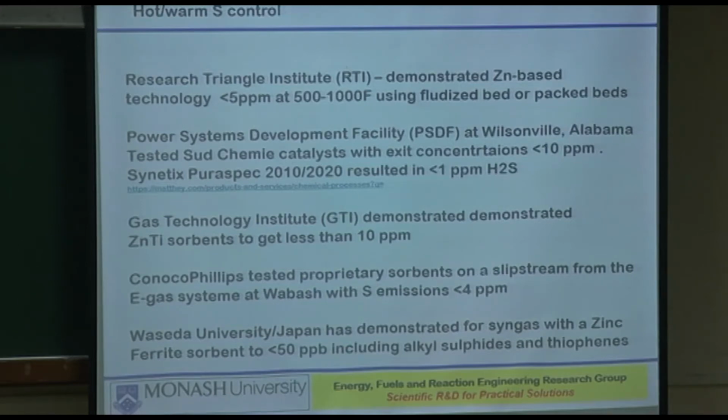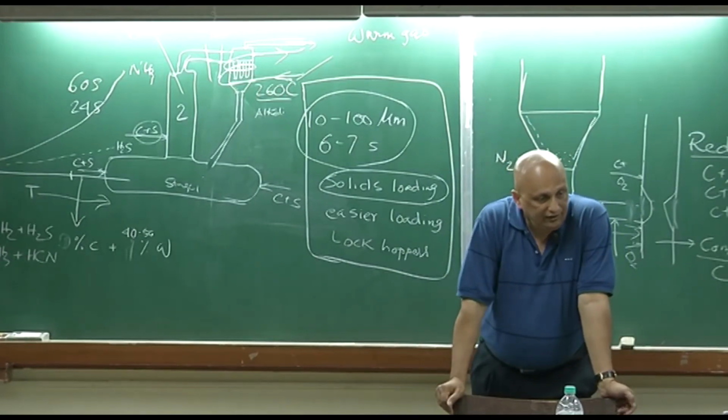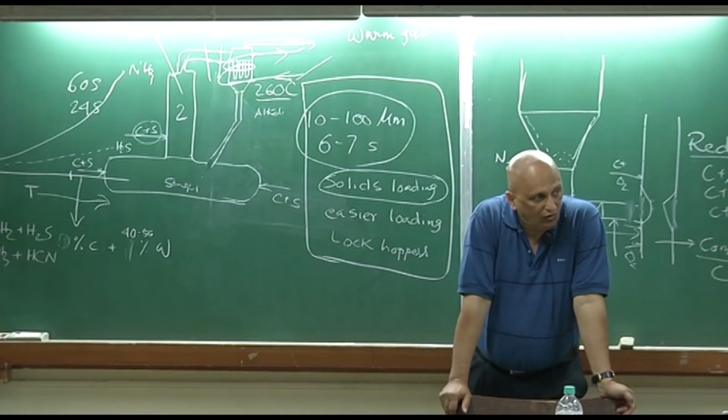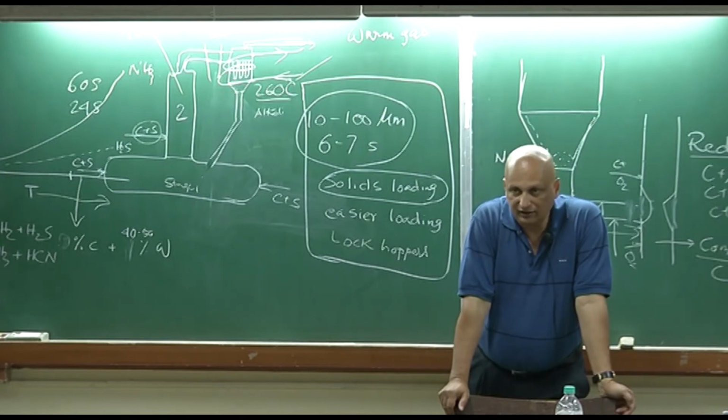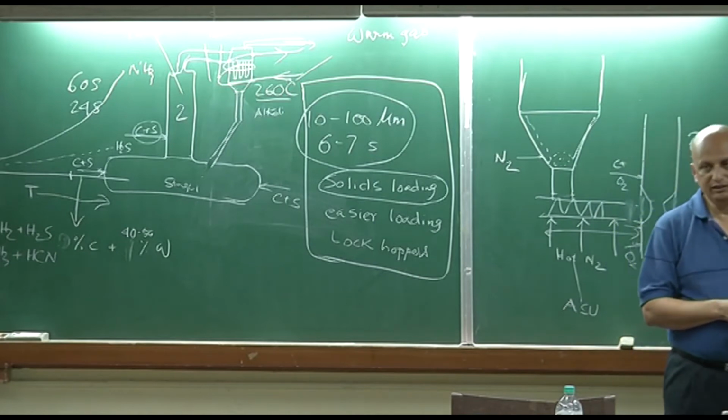But their filtration system is based on either a fluidized bed or a packed bed, and they have demonstrated this with zinc-based particles for sulfur control. So now we have come away from the metal filter. We are now talking about the specialized filters. This can work in either fluidized bed or packed bed. Both will provide adequate mixing or contact between the incoming sulfur gases and the particles in the bed. The bed, as you would expect, will obviously be filled with something that can tolerate the sulfur gases.